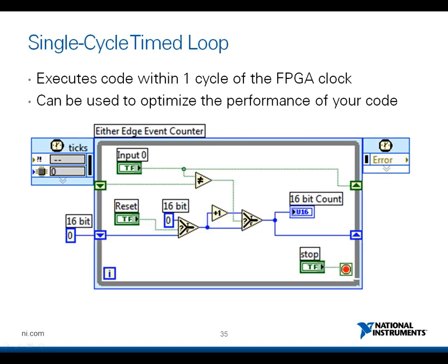In LabVIEW FPGA, you can also streamline the entire loop into one clock cycle by using the single cycle timed loop instead of the while loop. This can be used to further optimize the performance of your code in achieving faster timing.